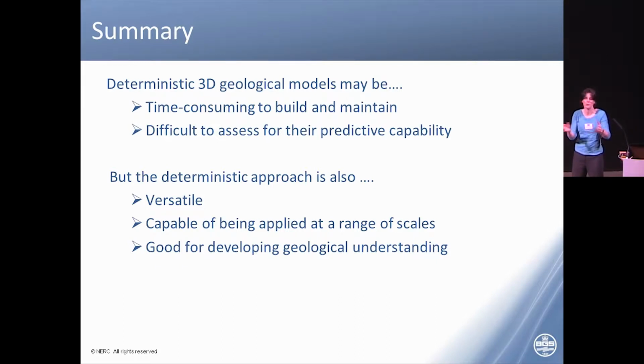I will often look at most of the boreholes in my model area before I select which ones to choose. So it's a way of trying to filter and evaluate which are the best ones. I'll try and take my cross-sections through areas where we've got the highest quality. So what we actually leave out of the model framework is the poorer quality ones anyway, if that makes sense.